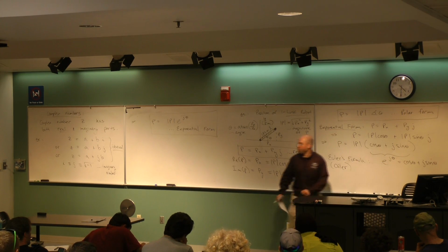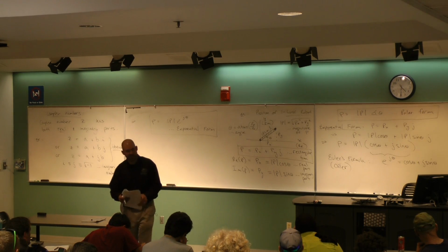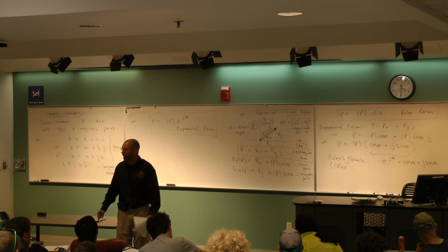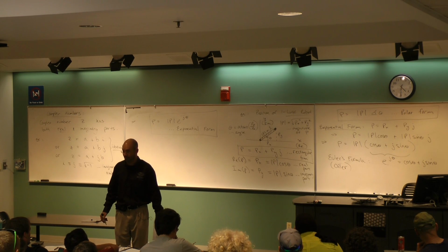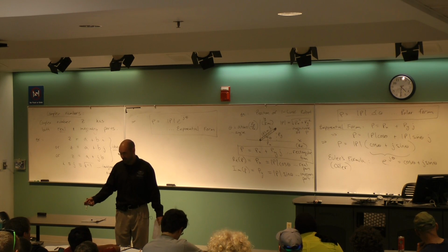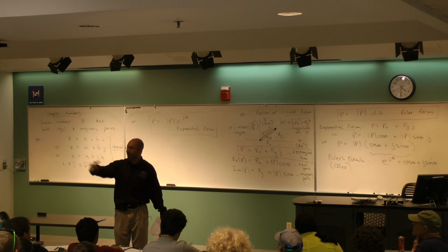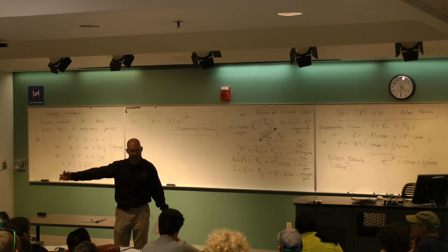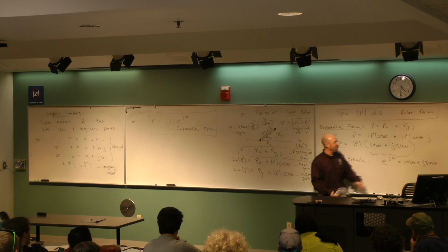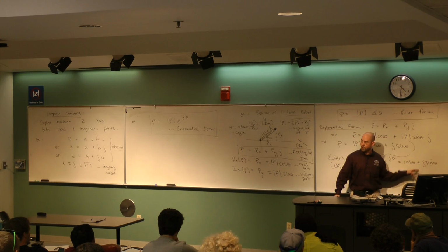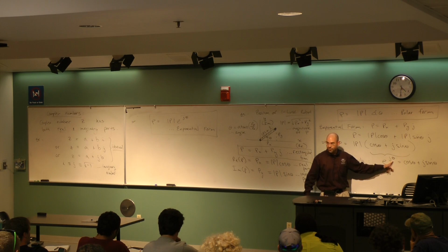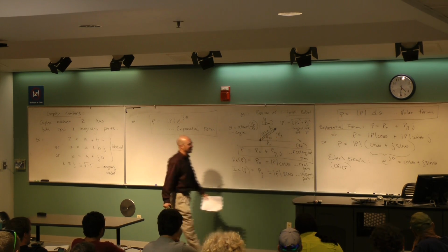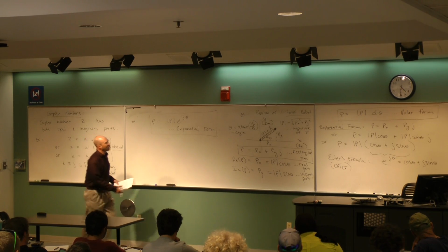So we're going to throw you for a loop. When we start using this stuff with e to the j thetas, it's very common in electrical engineering classrooms to write something like e to the j 59.6 degrees with a degree symbol on it. Math department would have a heart attack if they saw that. Hey, we do that in engineering all the time. It's convention, it's notation. If you try to evaluate it and spit out a number in rectangular form, you better have the theta in radians, or you get the wrong answer. So just to be clear, I'll make it clear when we're going to take that liberty and when we're not, and what it means.